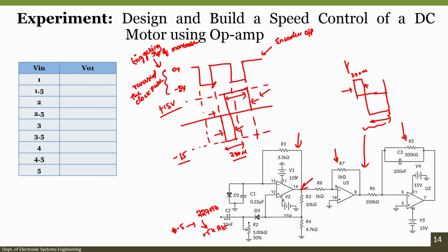The difference between a practical integrator and an ideal integrator is that the practical integrator should always have a resistance R5 in parallel to the capacitor that we have seen here. Even this integrator concept we have discussed in the previous course, please have a look, or you can send us a query so that we can give you further information about that.